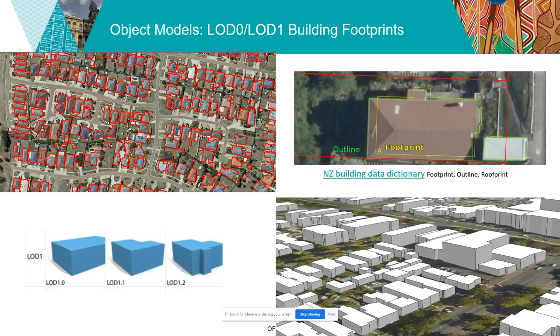There is a difference between a building footprint, the footprint of the building on the ground in its true location, and the building roof print, the outline of the roof in aerial imagery, including any building lean. This topic deserves its own presentation. It's important for us to have high quality imagery and LiDAR standards to reduce the building lean in our ortho imagery, to ensure that the features that are extracted are as close to the building footprint or its true location on the ground.